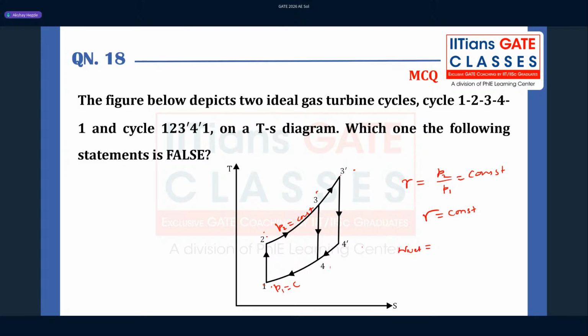That is going to be the temperature differences. So in other words, the enthalpy differences. Since it's an ideal cycle, we treat Cp to be constant. So the enthalpy differences between the turbine work and the compressor work, right? So that means work net depends on the temperature difference.